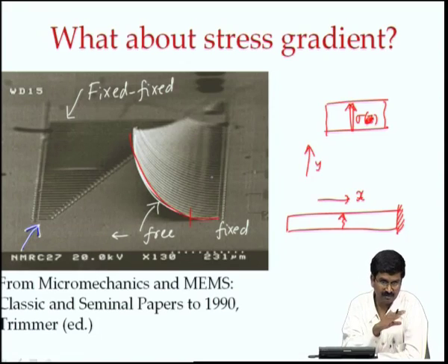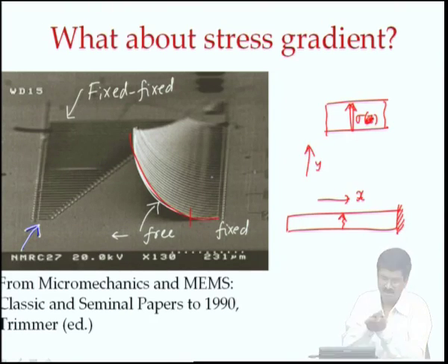When they are brought back to the lower temperature, this stress remains in them, because different materials that adhere to each other at high temperatures, when brought back to the lower temperature, have residual stress remaining in them. Other ways that residual stress can get created are oxidation and ion implantation, that is, when you add certain foreign substances into a substrate or a thin film, then you have residual stress.